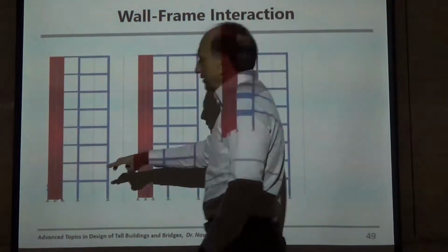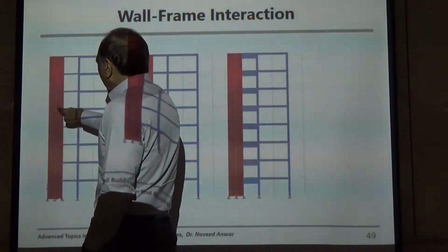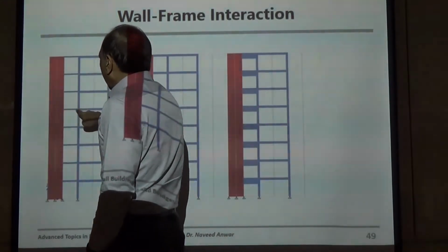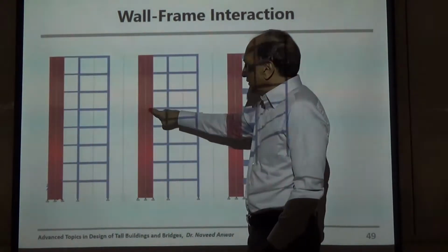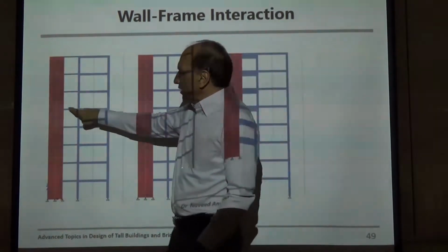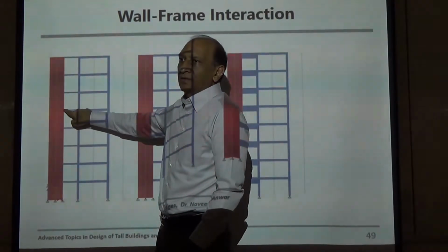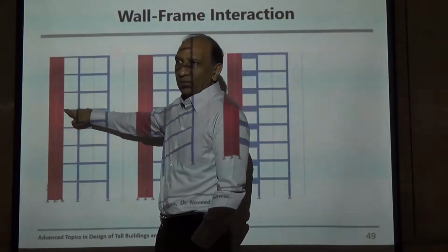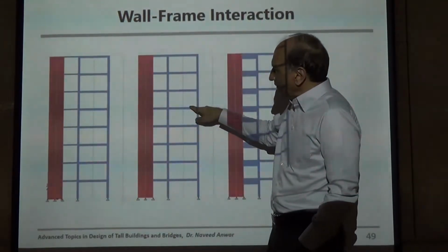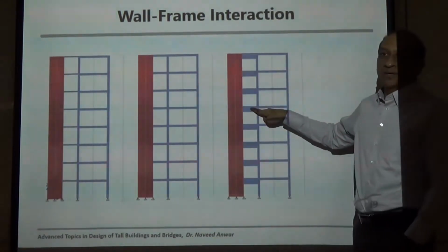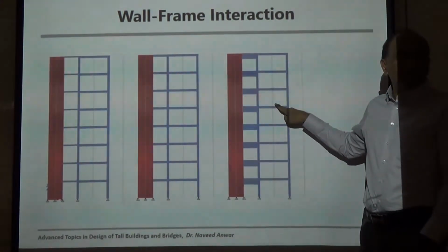So in this case, I put a shear wall here, and I put a normal beam, a smaller beam actually, that connects to the shear wall and the next column. Here I put the same beam, because this is a smaller span, so I put the beam small because that's what the gravity load will require. This one I use the same beam as for the long span and go directly here. Here I increase this beam size to be larger than this one.